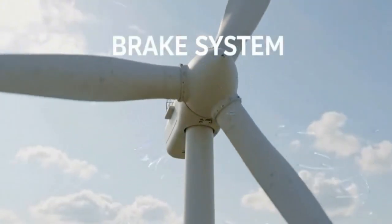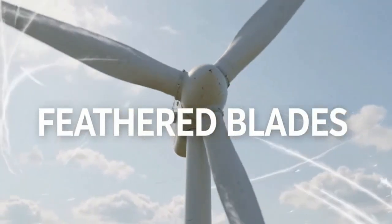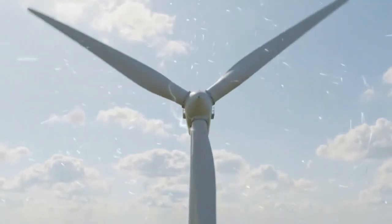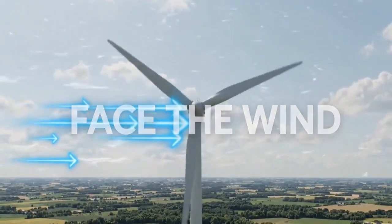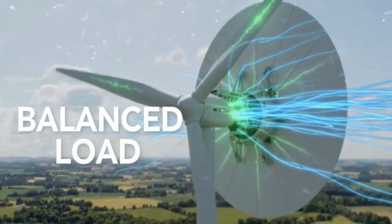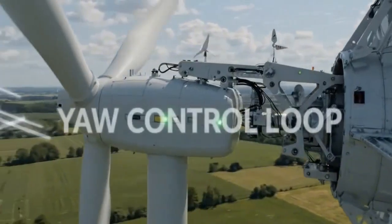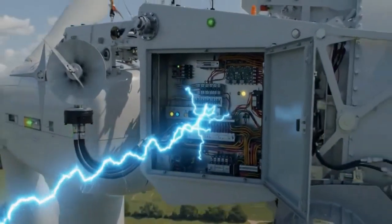When wind direction changes, the nacelle turns with it so the rotor can keep facing the incoming airflow. If the rotor is misaligned, some wind energy is lost and loads across the blades become less balanced. When the rotor is aligned, airflow across the rotor disc becomes more balanced and the turbine works more efficiently.